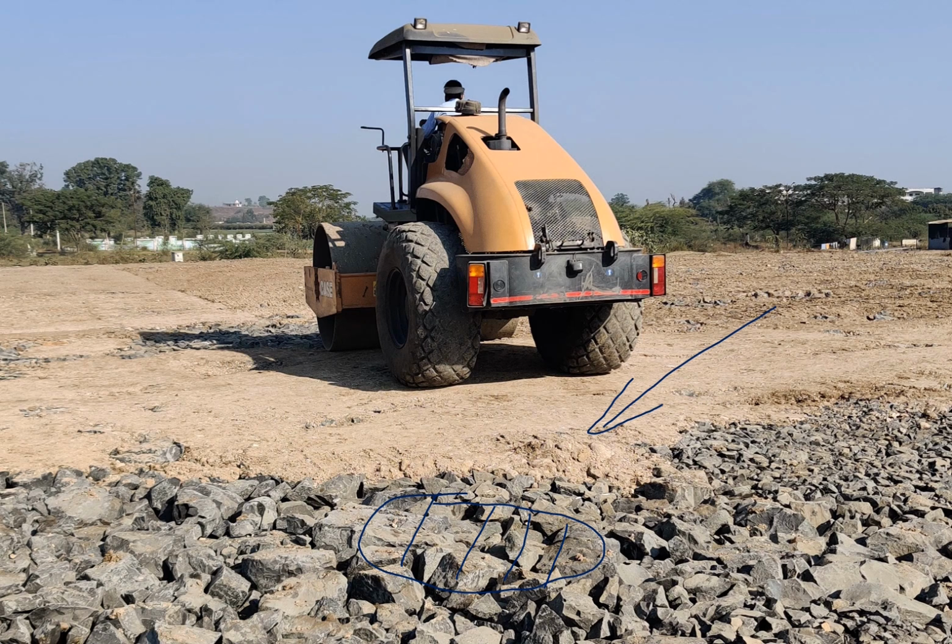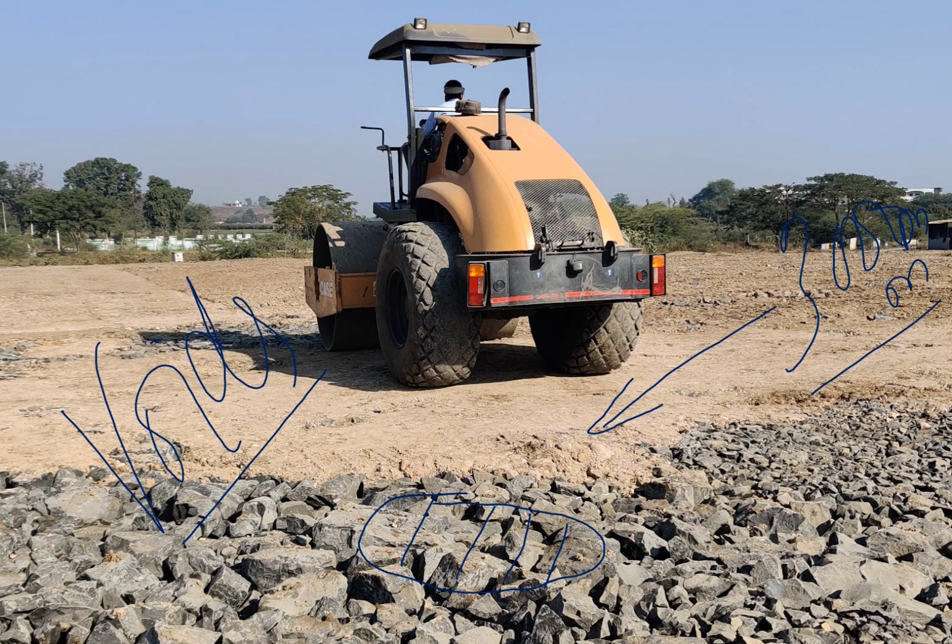The best way is to put the fine materials on top of it and then supply ample water, so that the fines will penetrate into the rockfill embankment, thereby minimizing the voids, which can be the biggest challenge as far as rockfill embankments of bigger heights are concerned, because the chances of settlement or long-term consolidation or movement of fine materials from top to bottom will be higher when rock of size 300 mm is laid in the rockfill embankment.